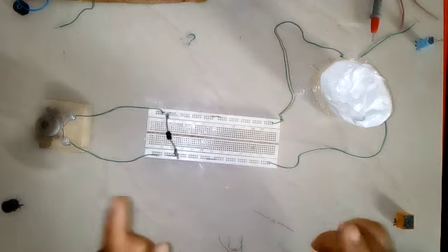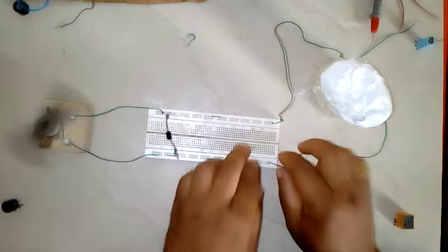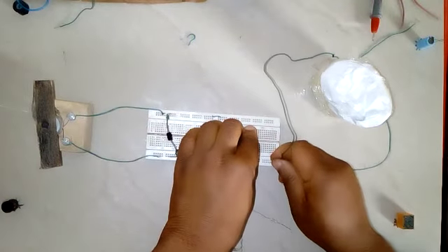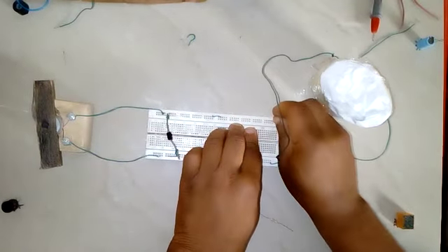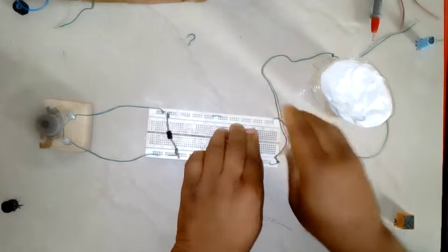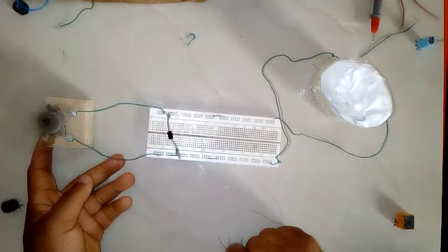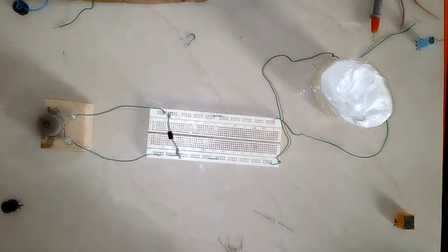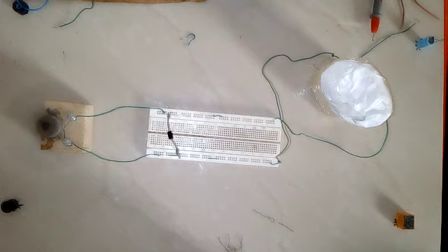Notice how the motor is turning now. Okay, I'm reversing the terminals. So positive comes here, negative goes there. And there you have it. It is operating at its full potential. This one is a better design because we're able to operate at our full voltage level. We are not robbed of 0.7 volts like we suffered in the earlier design.